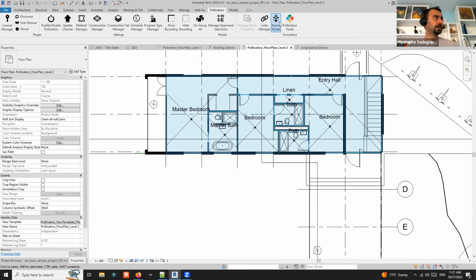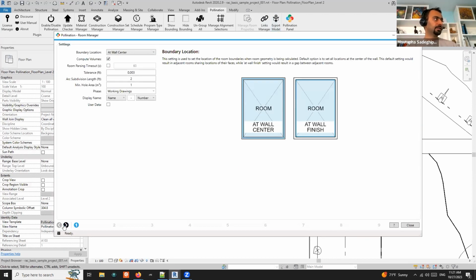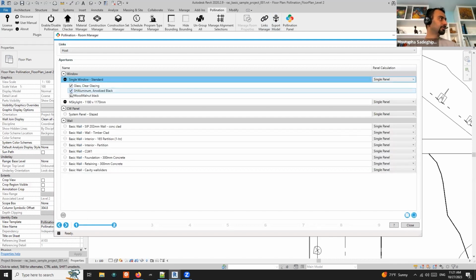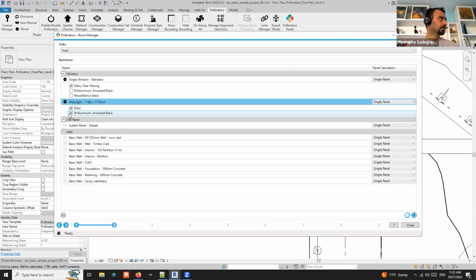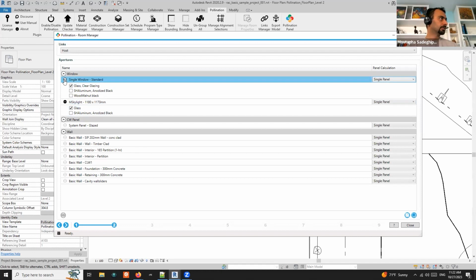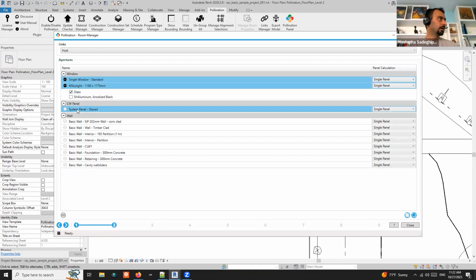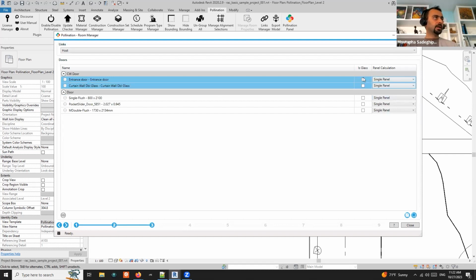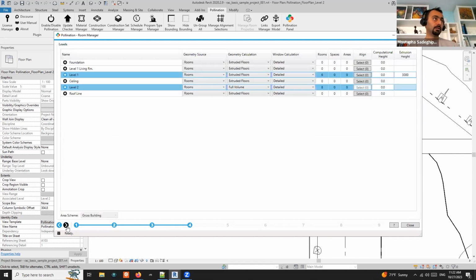So if I click on export model, everything that I have done before selected should be there. Apparently not. I don't know why. It should have been there. Okay, select the glass here. So I'm going to select this and this. I'm going to select the panel. I go next. Select these two doors and make them east glass. And I go next. Levels at least are still selected and stayed the same.